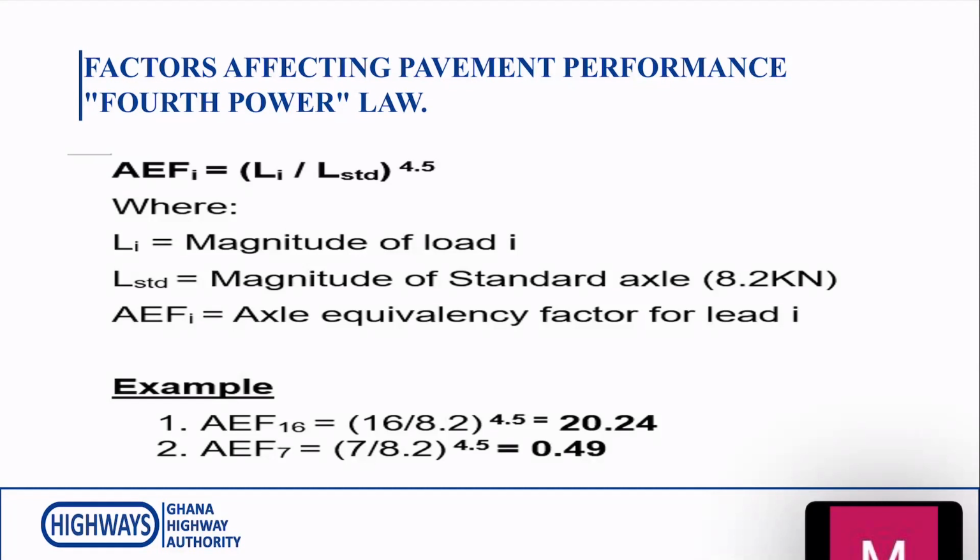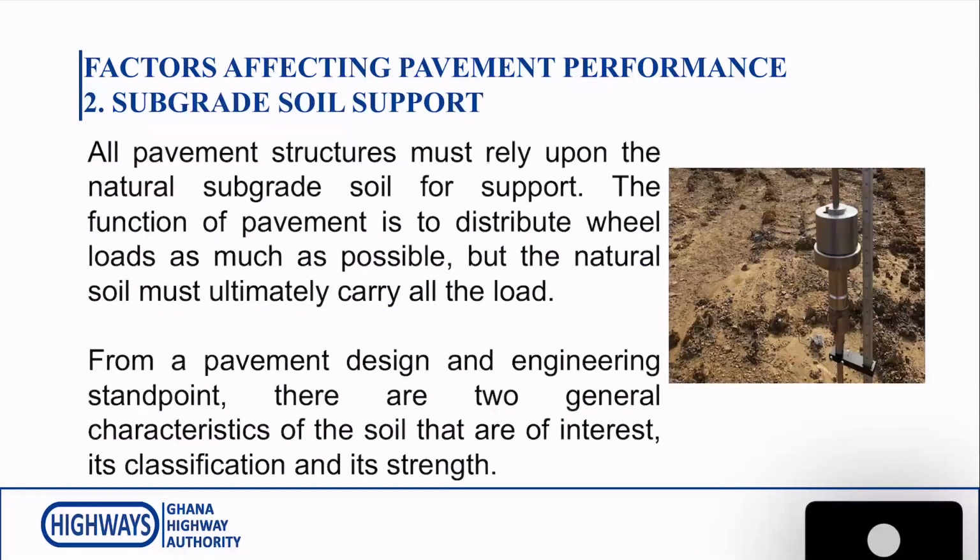And at the same time, if you look at the second example, a load of 7 tons, if that passes, it will cause half the damage of the standard load. So one has to be very particular about the damaging effect of traffic. It is very important to be able to estimate the axle equivalency factors and the damaging effect of the axles that we have on our roads.